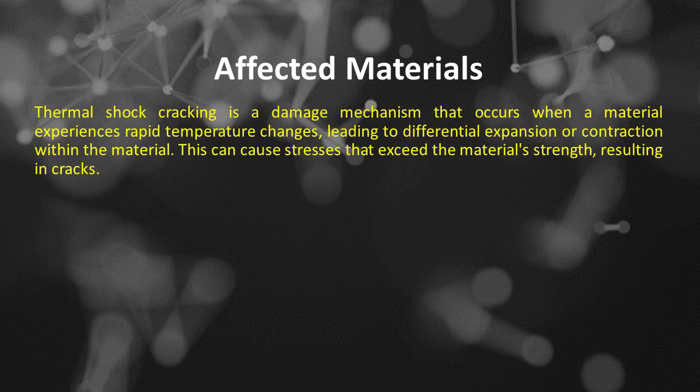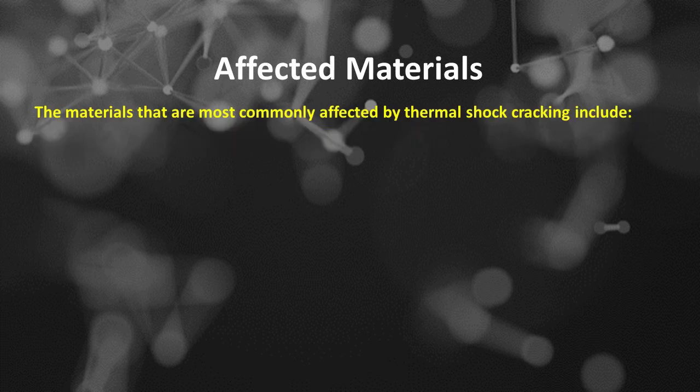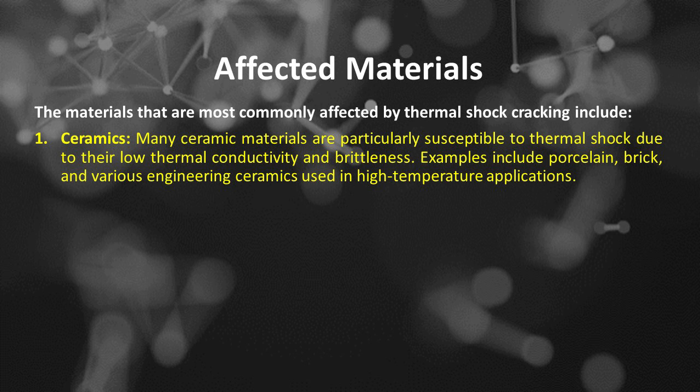Thermal shock cracking is a damage mechanism that occurs when a material experiences rapid temperature changes, leading to differential expansion or contraction within the material. This can cause stresses that exceed the material's strength, resulting in cracks. The materials that are most commonly affected by thermal shock cracking include: Number 1 is ceramics. Many ceramic materials are particularly susceptible to thermal shock due to their low thermal conductivity and brittleness. Examples include porcelain, brick, and various engineering ceramics used in high-temperature applications.